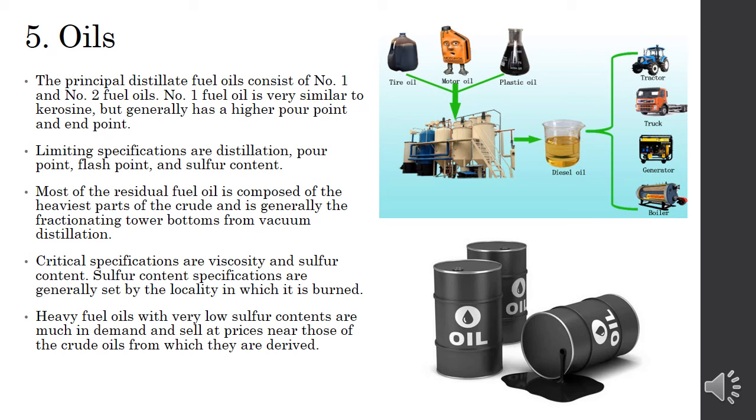Number 2 fuel oil is very similar to number 2 diesel fuel, contains cracked stock, and is blended from naphtha, kerosene, diesel, and cracked gas oils. Limiting specifications are sulfur content, pour point, distillation, and flash point.